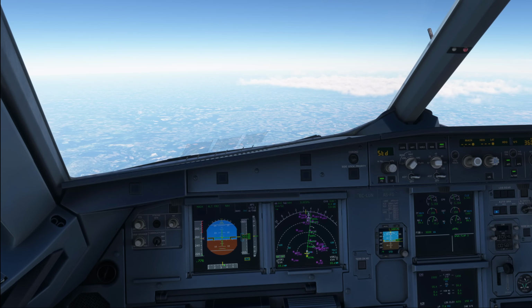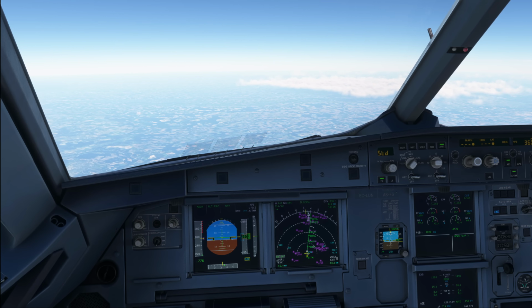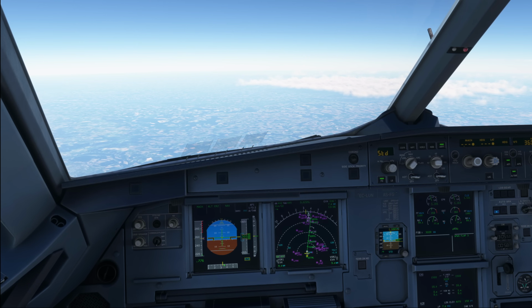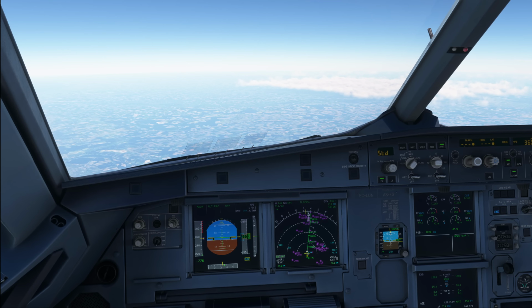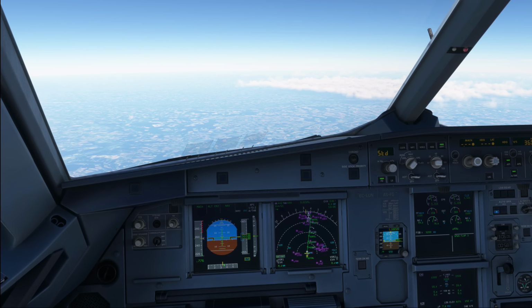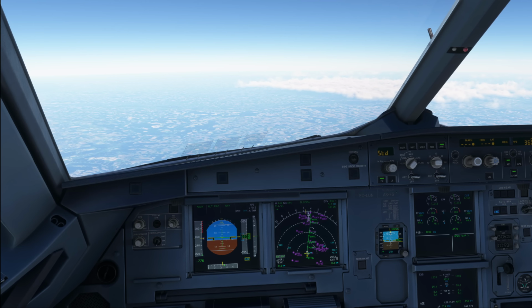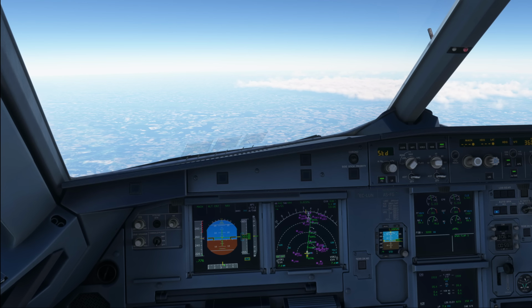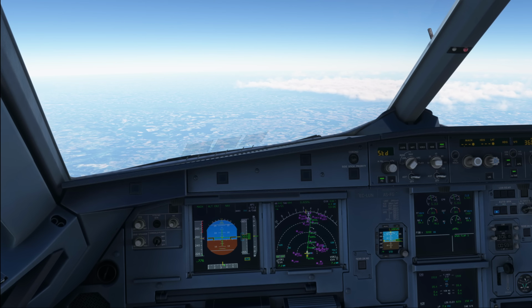Now, likewise, in terms of taxi, idle thrust is usually sufficient to move a light aircraft during taxi, and with IAE engines fitted, it can even be sufficient to move moderately, or in some cases even heavyweight aircraft. If necessary, the flight crew should apply only small thrust increases. Remember, excessive fuel burn is caused by excessive thrust and also requires more brake application, therefore resulting in increased brake wear as well, and thereby increasing cost. So if taxi takes a little bit longer but you can keep the engines in idle, that is certainly something that you should consider.